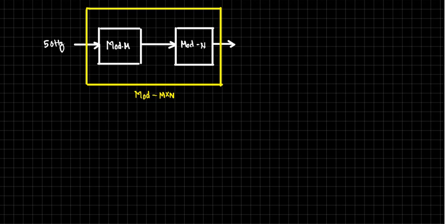Now if the input clock frequency is 50 hertz, these states will be repeated after m states. And for each of those states, at the output of mod m, the next counter, mod n, will be dividing it further by n. So overall it will be divided by mn. Now let m and n be 5 and 10 again. What is the output? You tell me. 50 divided by 50 is 1 hertz. So the output will be 1 hertz.